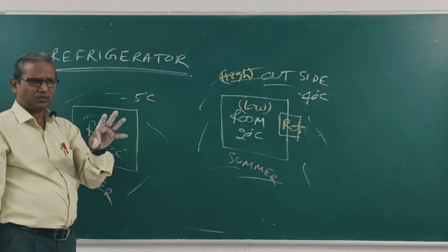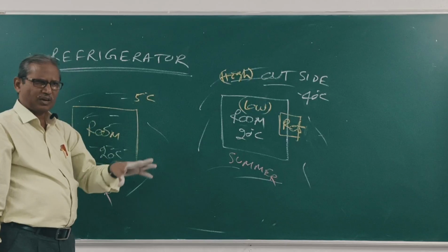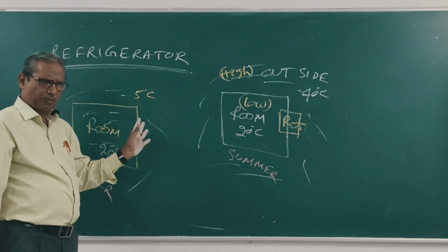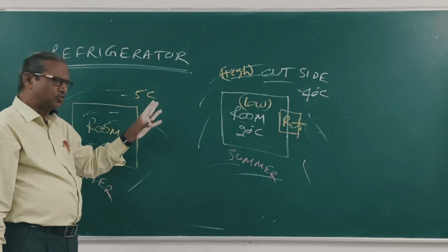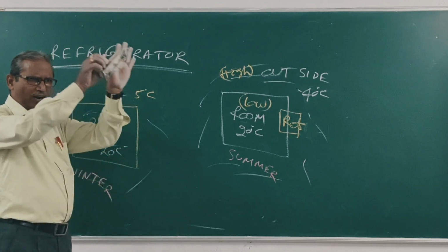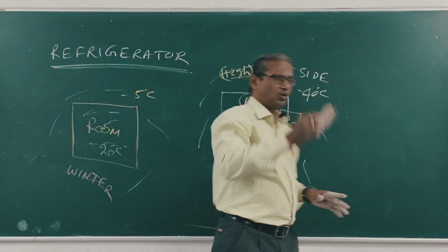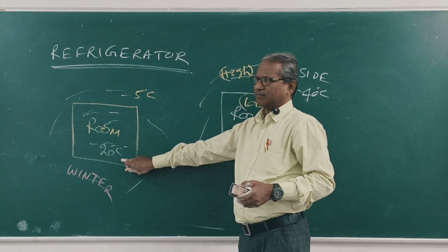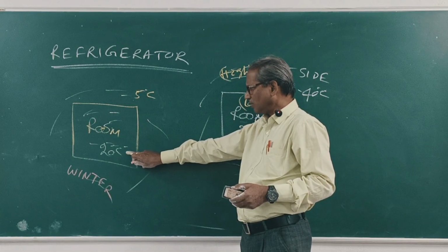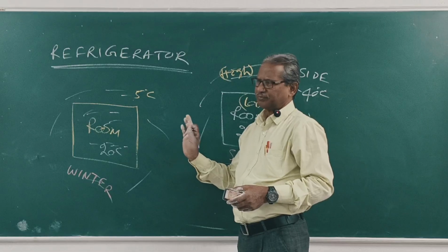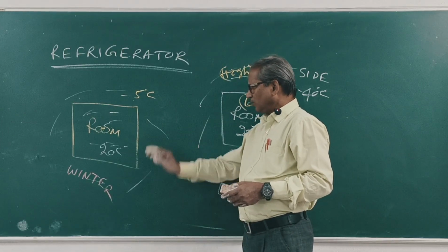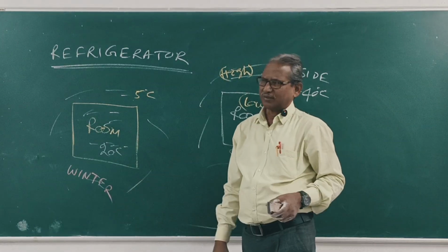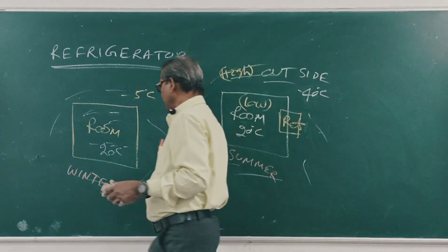Now this is today's condition, today's outside temperature is lower than our room temperature. But since the room is 20 centigrade, the heat can transfer from room to outside from the roof, or it can be lost to the outside surrounding. Clear? Our roof is cold, our walls are also cool surfaces, so this heat may be rejected, lost. This heat may be lost, transferred from inside to outside. Clear? But to maintain the room at 20 centigrade, heat will be transferred from outside to inside with the help of a device that is called heat pump.